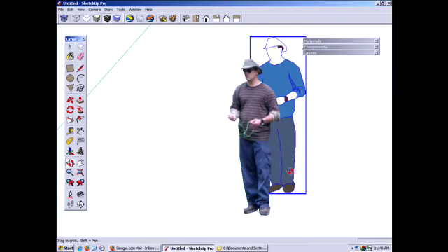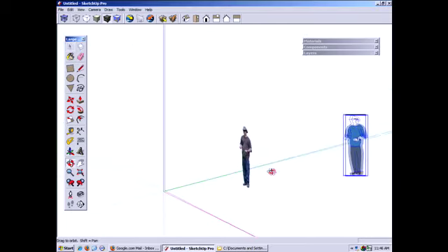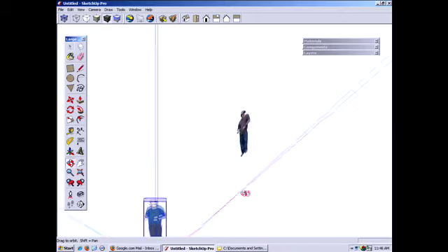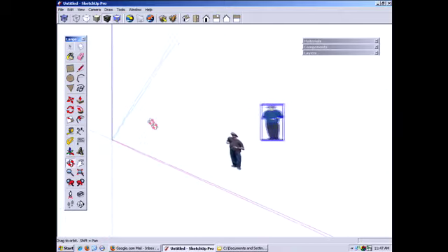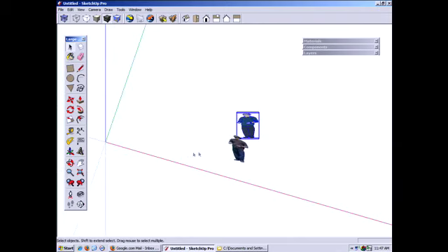Create this. We can't even get this to work because the axis that it's rotating about is over here, and the component's over here. A face me component works on the axis. So if the axis is right here, it works like this. If the axis is over here, it works like this. So by putting that axis far away, we've created an awful, useless component.